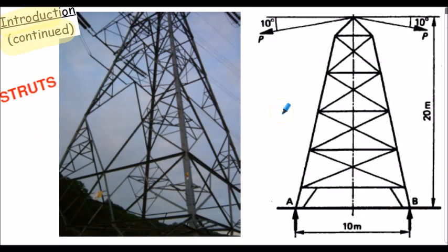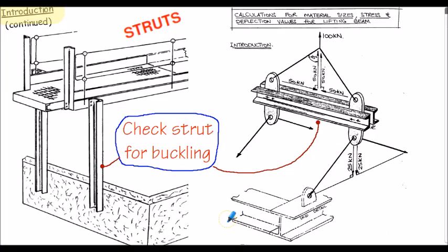With structures such as electricity pylons, we often use bracing effects to help reduce buckling considerations. Again, members need to be checked that if they're in compression, they do not buckle. Here are two designs I was involved with when employed as a junior design draftsman many years ago.